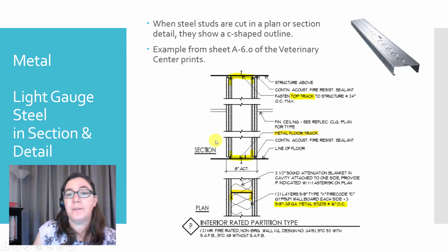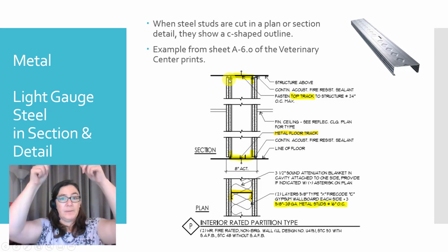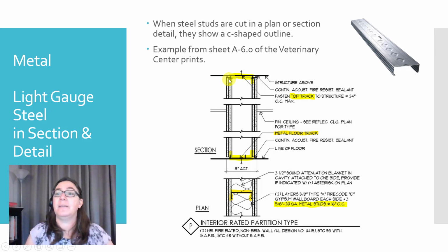All right, and so we're going to see the steel studs three places. First of all, they are at the top track and the bottom track. All right, hard to see, all right, because they're so thin. And also, I didn't highlight it, but we would be looking at the edges of a vertical steel stud right here in the middle of the wall.